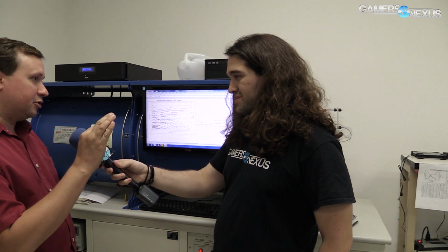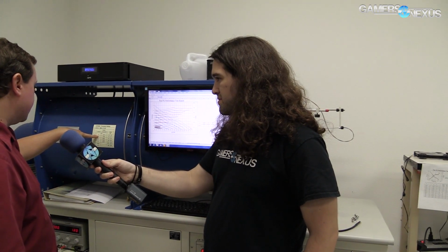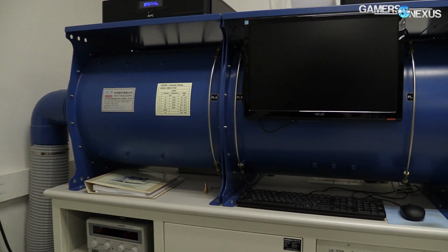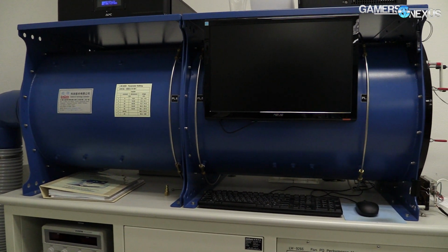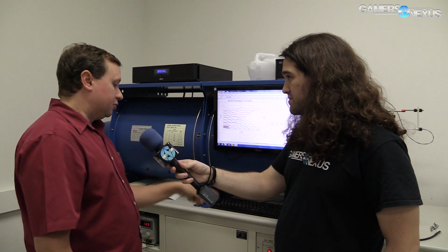In this plate here in the middle, there's a series of valves that start out about 1/2 inch in diameter and go all the way up to several inches in diameter. And it can open 1 or more valves depending on the type of test that it's doing. This chart here shows the smallest valve is 8 millimeters in diameter, and the largest is 42. And it tells you the CFM range for whatever combination of valves you have open at that time. So when measuring the differential pressure across here and knowing the exact diameter of the valve, it knows the barometric pressure and it knows the temperature and humidity of the air, calculates the air density, and can then calculate the exact CFM flowing through the system.